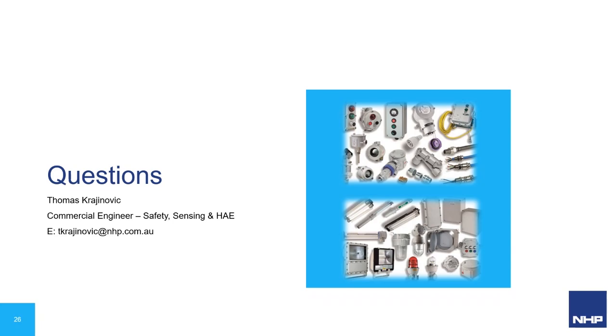Thanks, Tom. We have another question. Can I modify hazardous area equipment myself? That is, can I add another bung to a pre-engineered enclosure? So no modifications can be made. This includes, like I was saying before, addition of new items inside the enclosure or new entries or anything like that. All of this needs to be checked and verified by the manufacturer to make sure that the enclosure is still going to provide the protection that it's meant to provide.